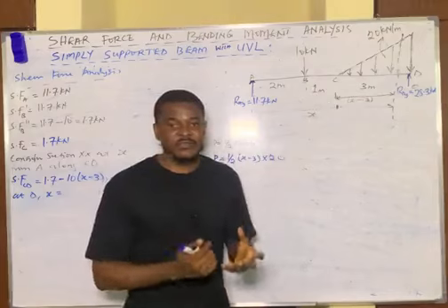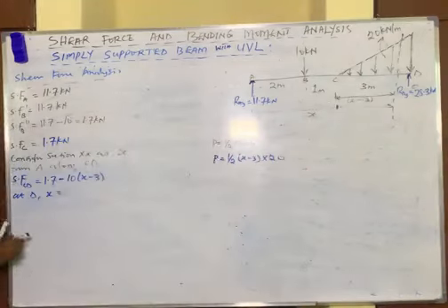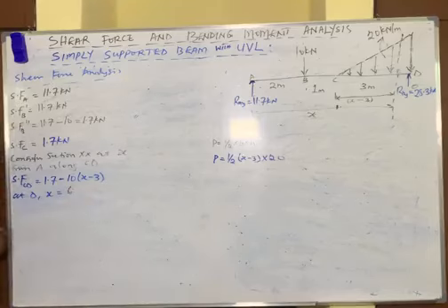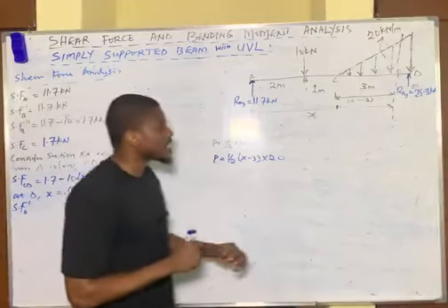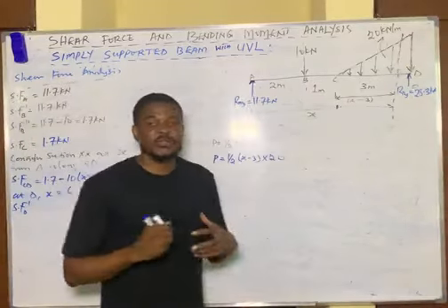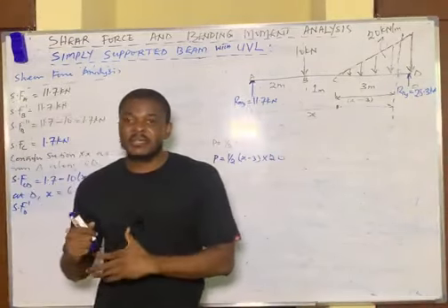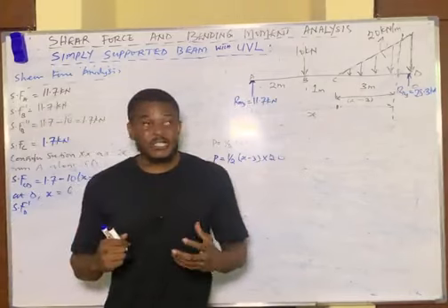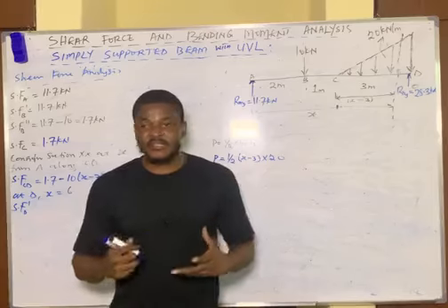X now has a value, right? So at point D, x equals 6. So you simply plug that into this equation. You're now going to have that shear force at D initially. Since there's a force at point D, we simply call that shear force prime, which means shear force initially at point D, because at point D, we have a force existing there.